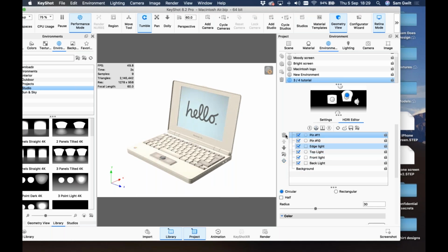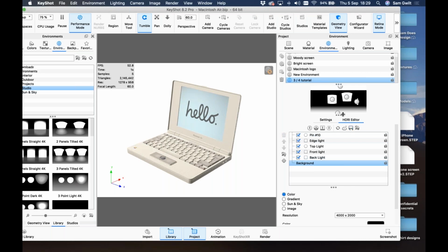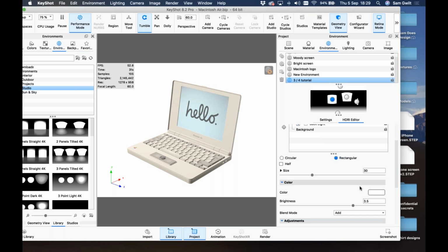So why is it important to make things realistic? Well, I know, for example, after researching 3-point lighting and lighting techniques like that, that a lot of photographers use what they call softboxes. And a softbox is essentially something that's going to diffuse the light to be as wide as possible. Now, what that means is it's going to make shadows that aren't so sharp, because the smaller the points are and the brighter they have to become to make the same light, the sharper the shadows are going to get.